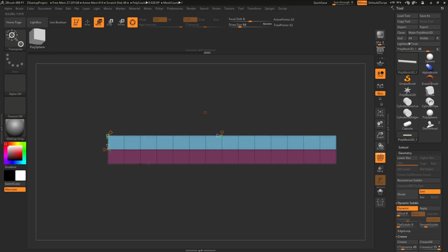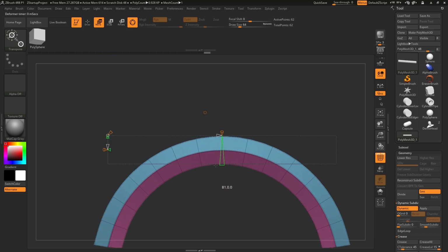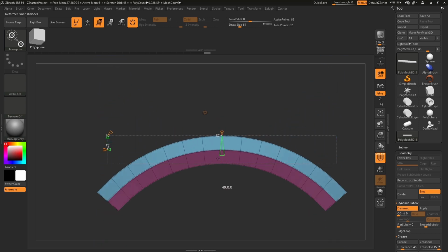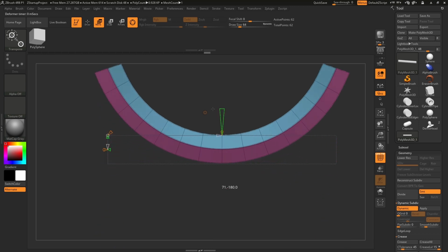So we want to make sure we're in this horizontal view here, so just rotate your model, holding Shift to lock it into a horizontal orthographic view. And then we want to locate this set of cones here, and find the one that's labeled angle. It should be this one that's pointing down here, and we want to click this and then drag. As you click and drag, you're going to notice it's going to perform a bend on your mesh. Moving up and down will create a different bend across that surface.